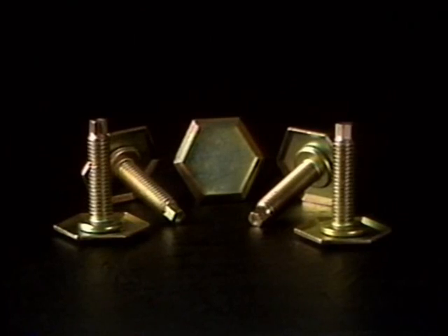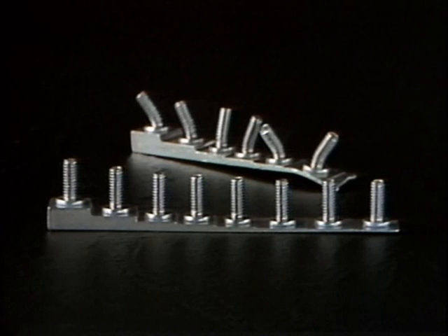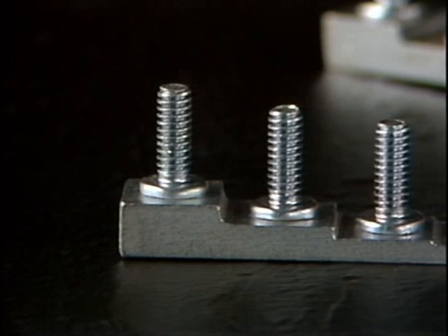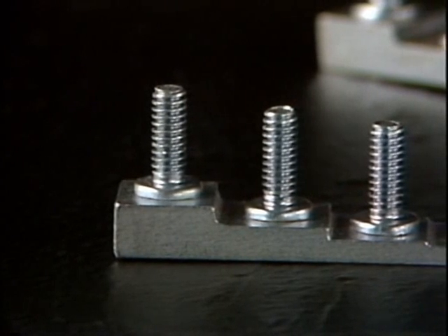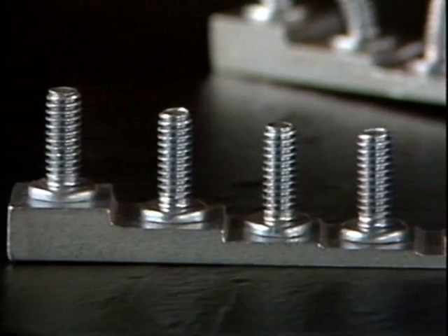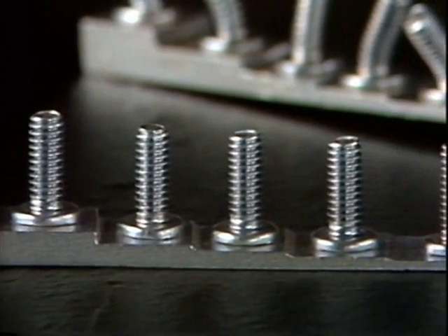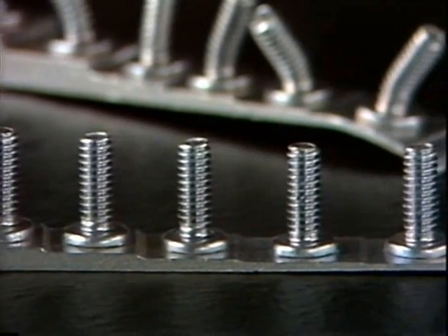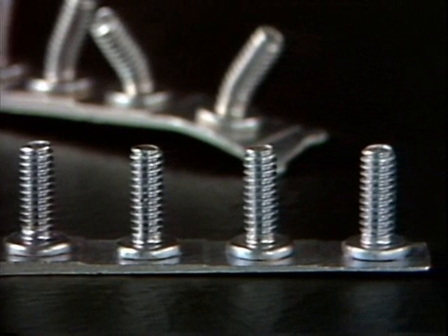A beneficial feature of projection welding is the smooth and clean appearance this process provides. In many applications, the weld assembly is ready for paint or plating. Another feature of projection welding is greater strength. The projection weld fastener can be welded to thicker material, obtaining greater penetration into the parent metal than can be achieved with spot welding. As you can see with projection welding, a wide range of material thickness can be accommodated.